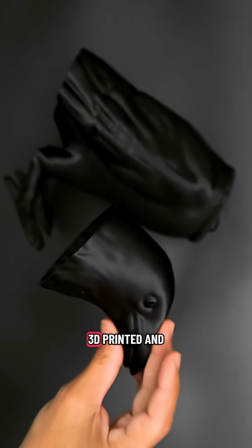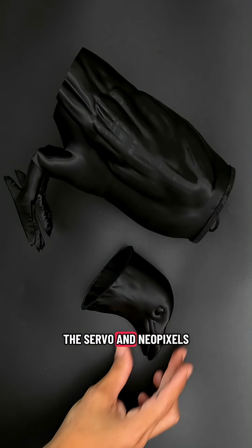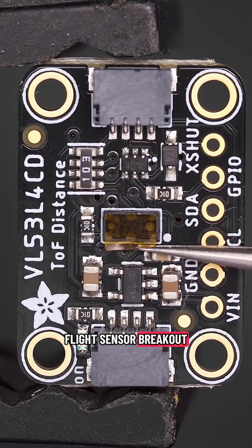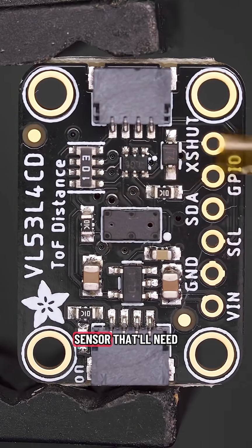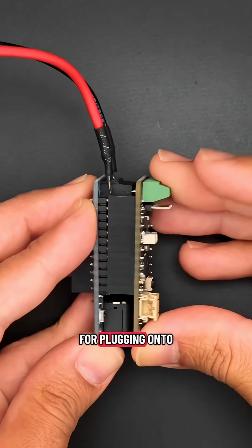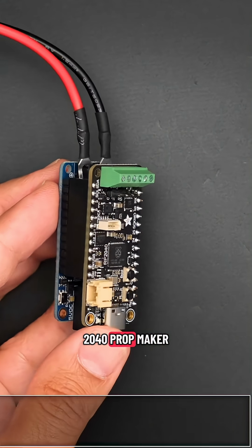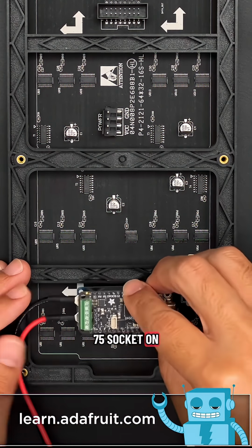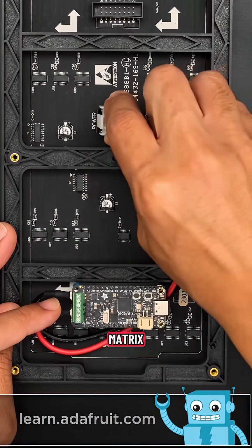The Raven is 3D printed and hollow for fitting the servo and neopixels. The time-of-flight sensor breakout has a protective sticker over the sensor that'll need to be removed. The Matrix Feather Wing is set up with headers for plugging onto the bottom of the RP2040 Prop Maker Feather. The two can then be plugged into the Hub 75 socket on the back of the RGB LED matrix.